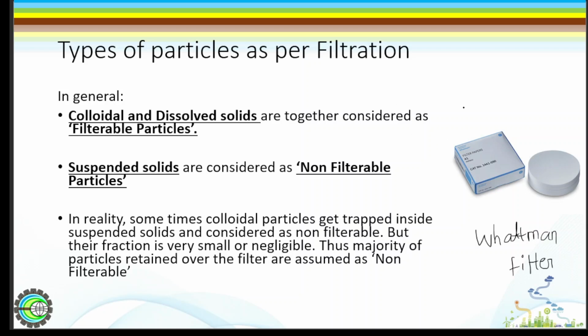Suppose we choose a pore size of 1.25 micrometers, it ensures that particles greater than 1.25 micrometers will remain on top of the filter layer, and the remaining particles less than 1.25 micrometers will pass through the filter.